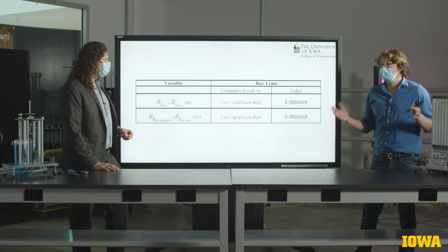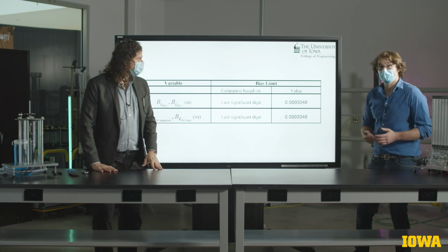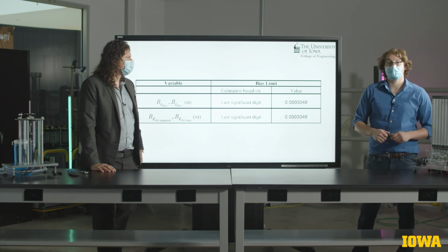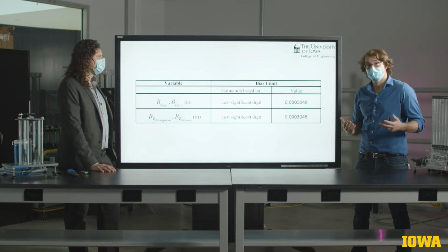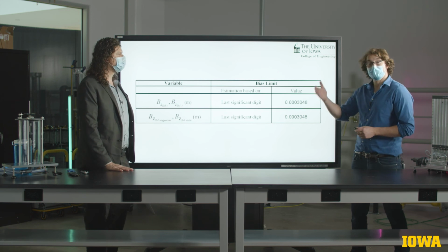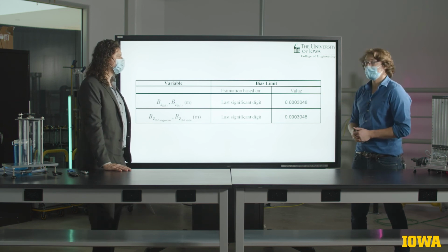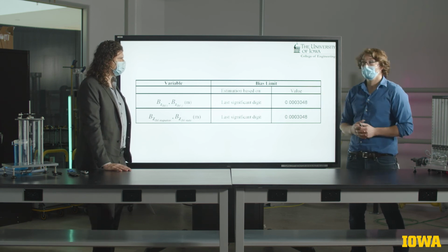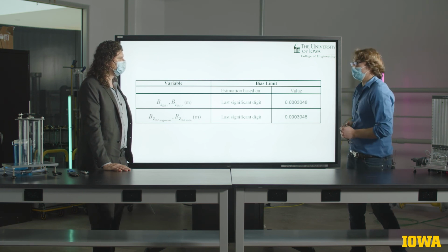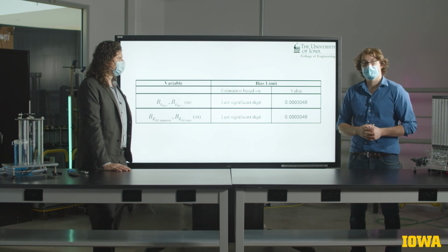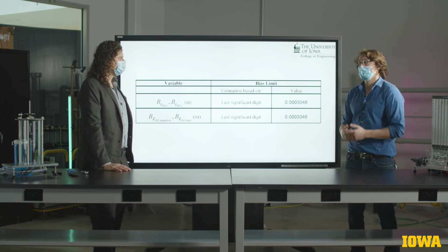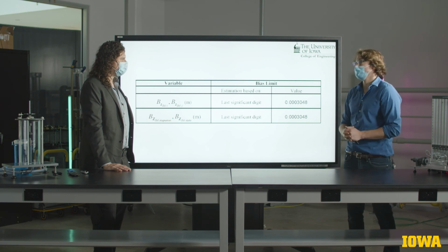That's right. And remember, once again, the precision limit is not being calculated through propagation. It's being calculated from the scatter in the friction factor. Remember that when Ricardo was conducting the pressure drop measurements along the length of the pipe, he plugged into taps 3 and 4 10 times each, which will give you 10 pressure drops, which you can non-dimensionalize into friction factors. So you have a whole sample of f values that you can turn into a precision limit.